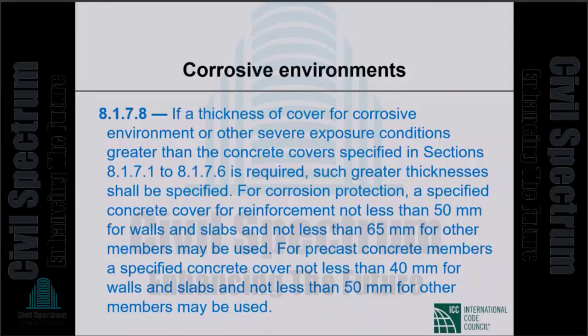Corrosive environments. Okay, this is important stuff for Bangladesh. This is why I kept it here. The cover that was being referenced from earlier. If a thickness of cover for corrosive environment or other severe exposure conditions greater than the concrete cover specified in section such and such is required, such greater thickness shall be specified.